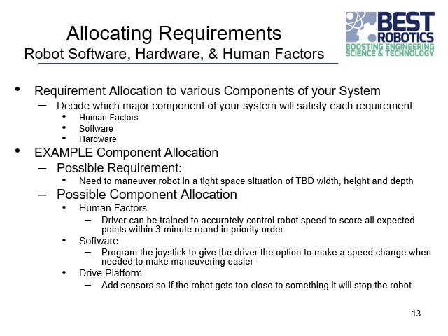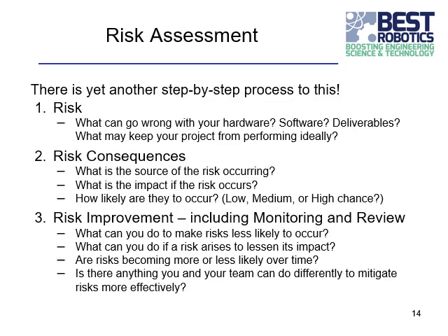So perhaps programming through the joystick to give that option. And then perhaps one of the capabilities you have in hardware is having sensors. So it could sense that it's getting close to something and automatically slow down or stop the robot. So these are ways that maneuvering the robot in a tight space may be spread across those three components.